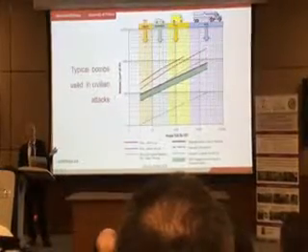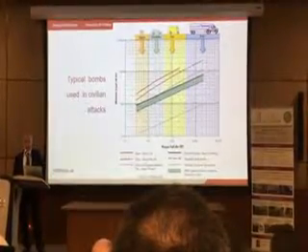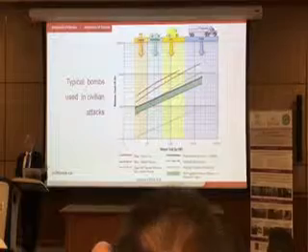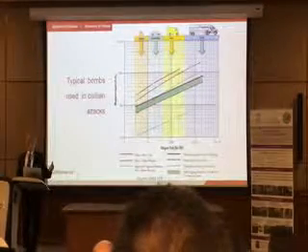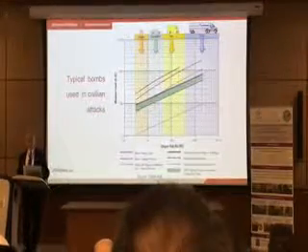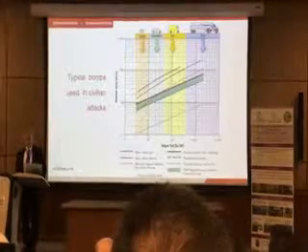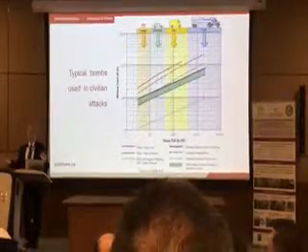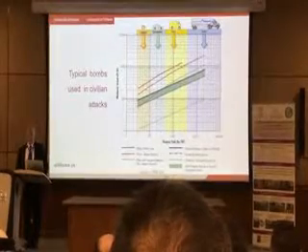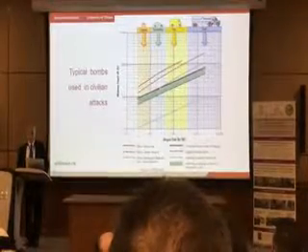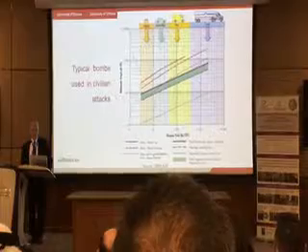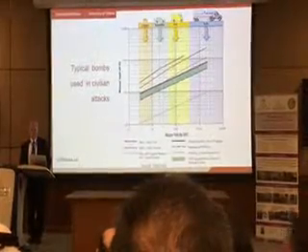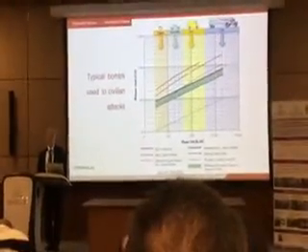It's now going to about 40 meters. Then you get walls, masonry walls, and fragments of that flying in and killing people. And then these dotted lines are glass fragments. So as standoff distance increases, which means you're moving up on this horizontal axis, then of course damage decreases.